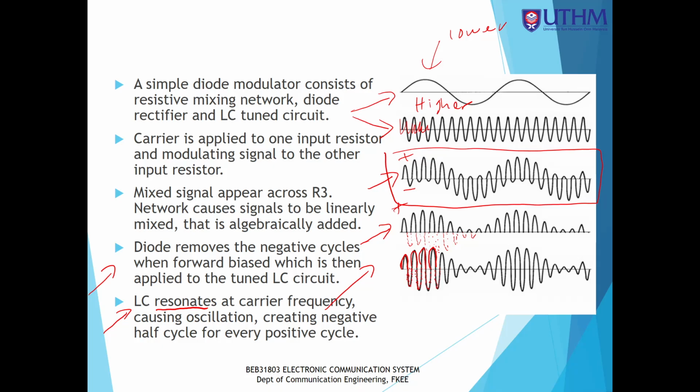So what happens is that when the signal goes from the positive to the negative cycle, the transistor will clip off the negative peak cycle. It will clip off the negative cycle of the signal. Okay, so this is actually the output. This is what happens when the voltage at the base is less than the threshold.